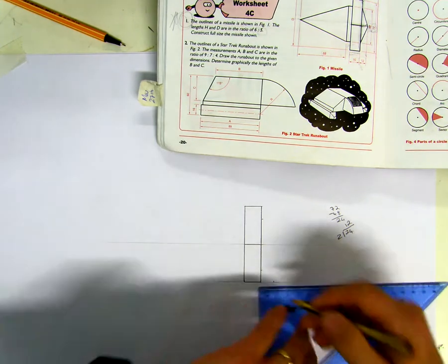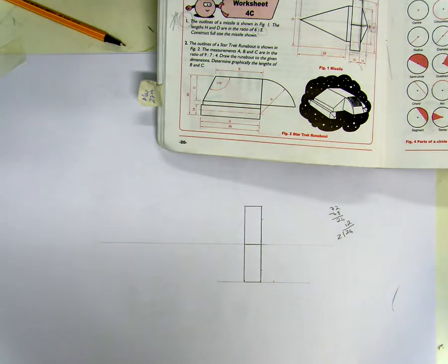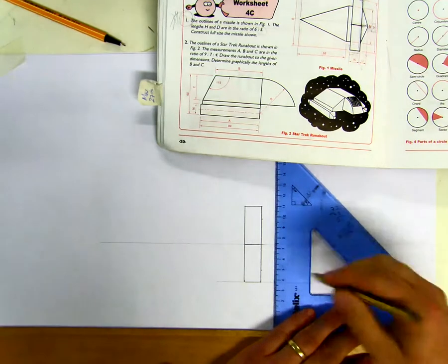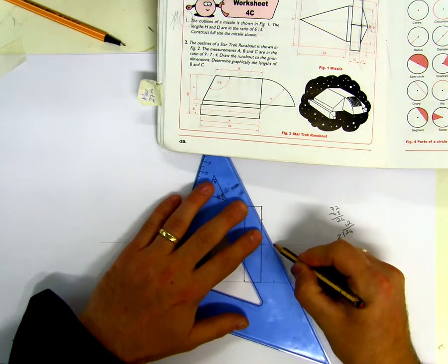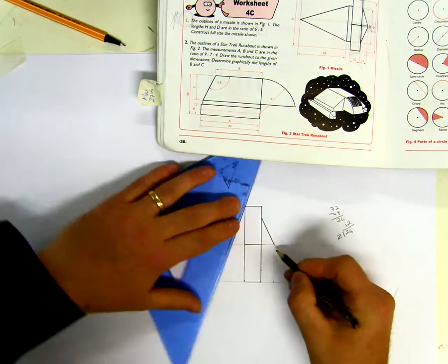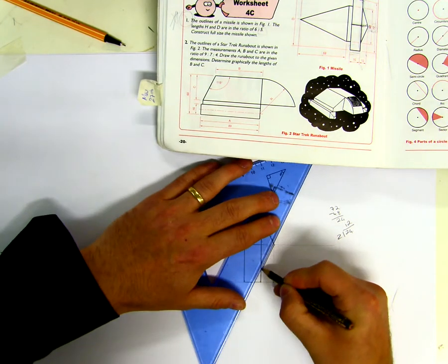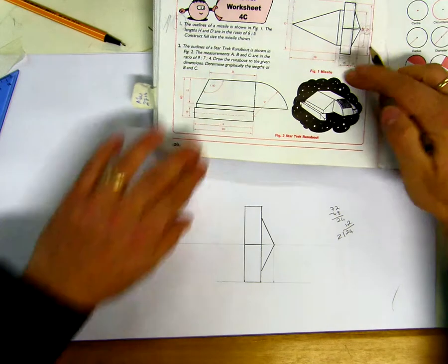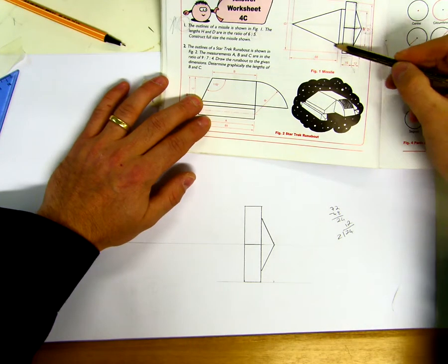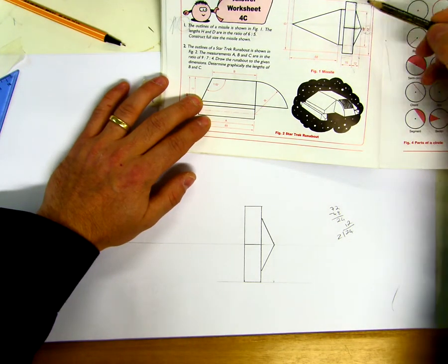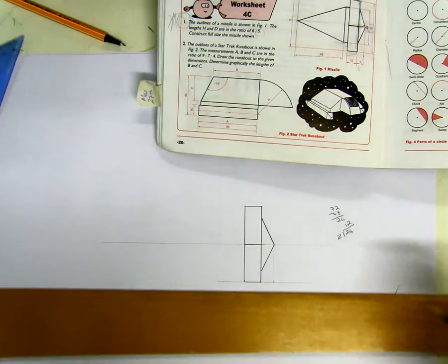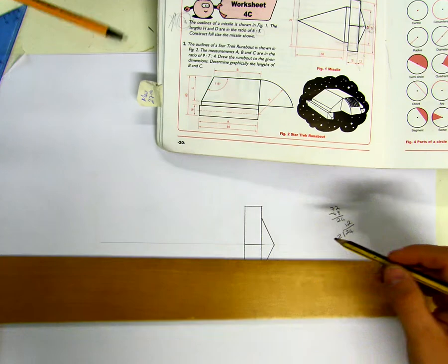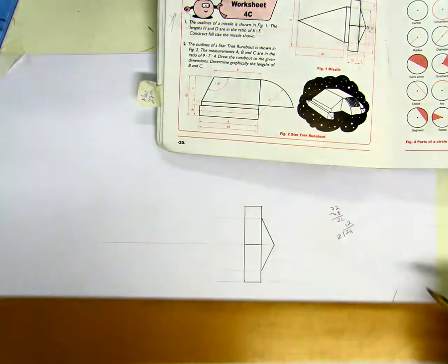So it's all about points when they contact each other. Okay, so we're going to draw a line up there lightly. Where that line intersects here, we're going to join back to our 12 line. Where it intersects here, we'll join back to our other 12 line. That's done. So we can see in our drawing, that point comes across and is in line with this point. That point comes across in line with this point. The center comes across and is in line with this point. So we're going to bring these lines across lightly. These lines are construction lines across.